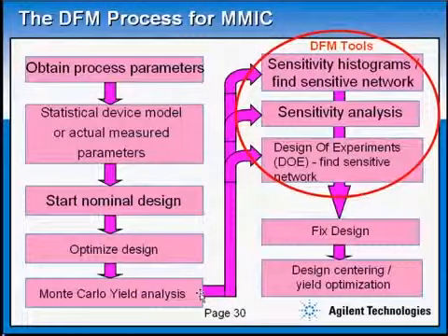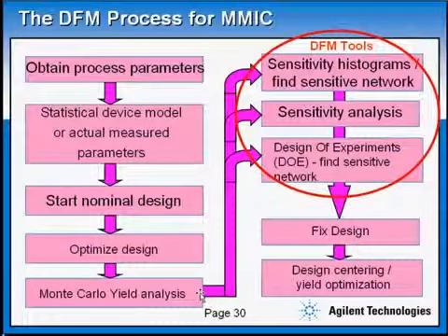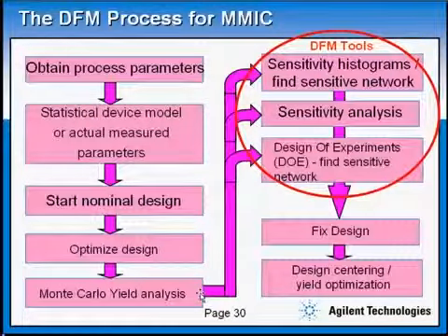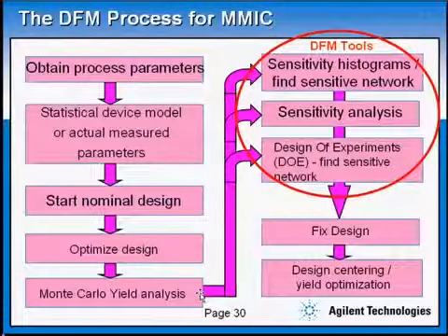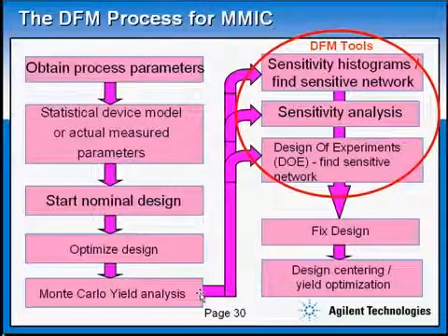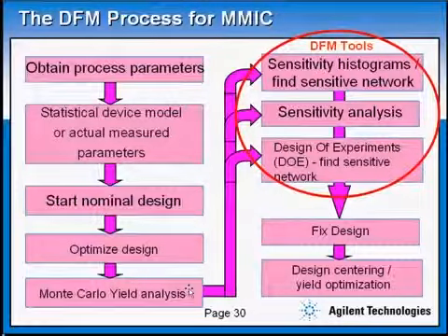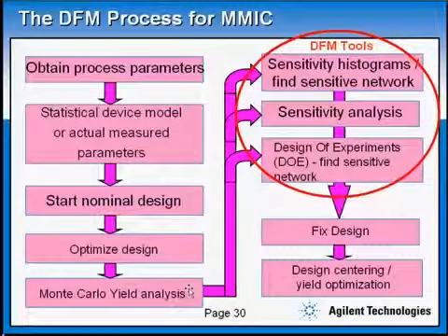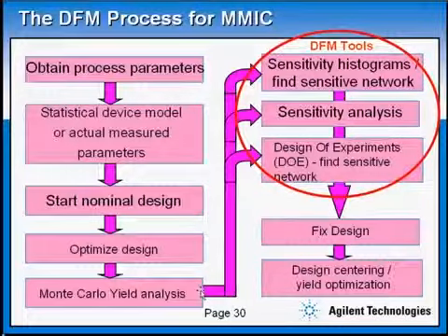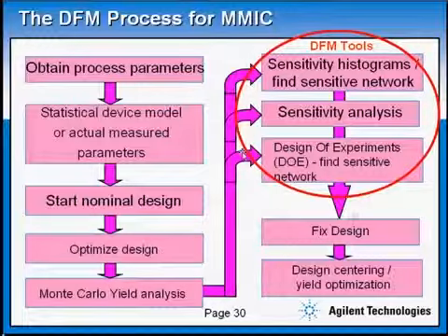This is the art of doing DFM or robust design in MMIC. So again, I repeat, many people think yield analysis is part of statistical design and making robust circuits. No, this is not true. Yield analysis is nothing but a check to see whether your design is going to have high yield or low yield, or whether your design will make a first pass success or not. It does not fix your design. It does not transform your design into a robust circuit. So Monte Carlo yield analysis tells you there's a problem.